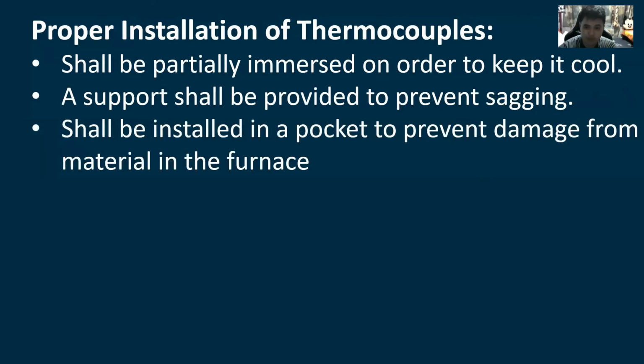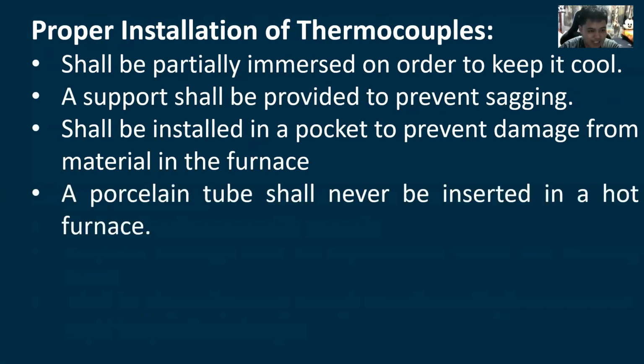Another proper installation: it shall be partially immersed in order to keep it cool. A support shall be provided to prevent sagging. It shall be installed in a pocket to prevent damage from material in the furnace. A porcelain tube shall never be inserted in a hot furnace.